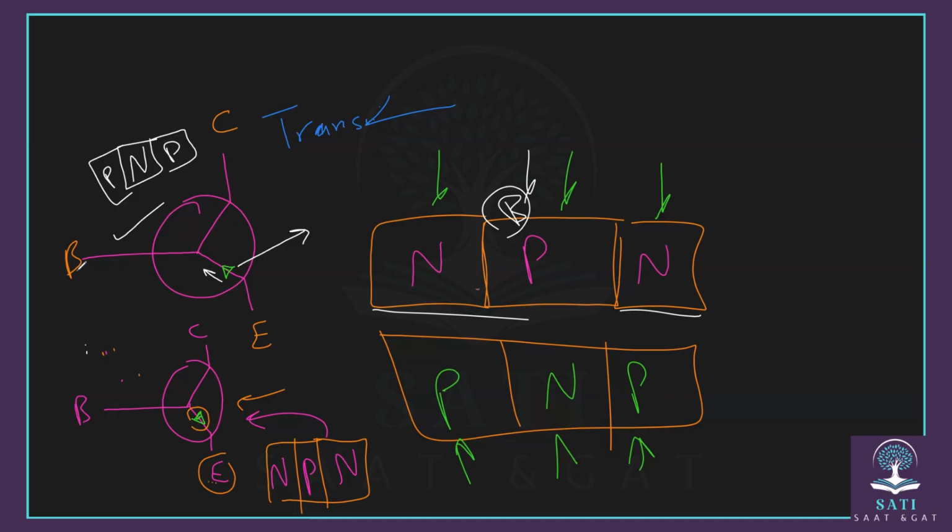Okay, how do we get the gain of current in a transistor? The gain of current equals the current of the collector over the current of the base. You find the current of the base and the current of the collector, and you divide to get it.